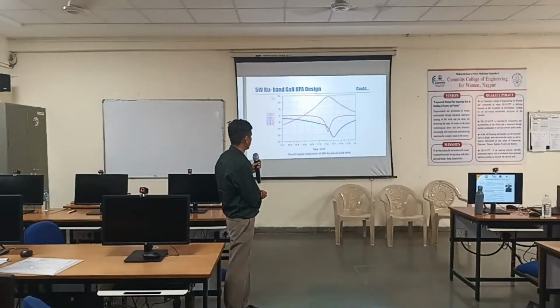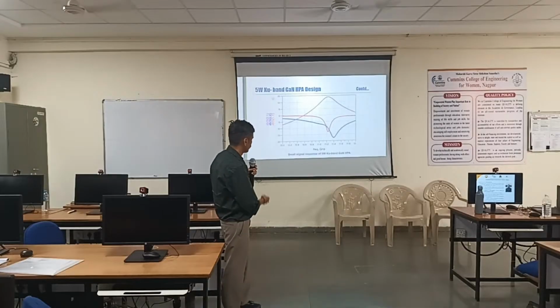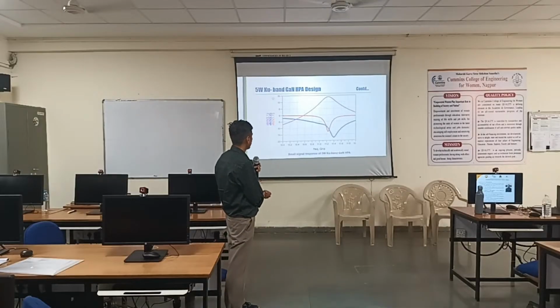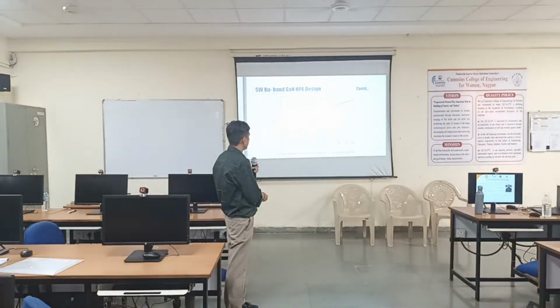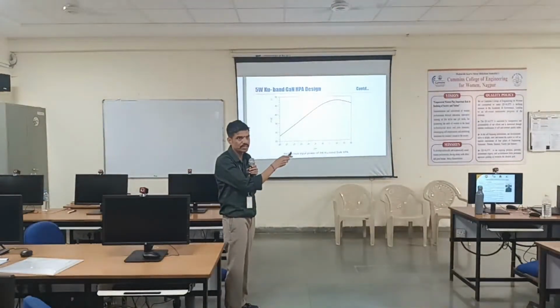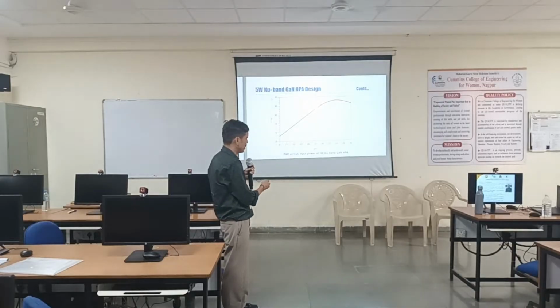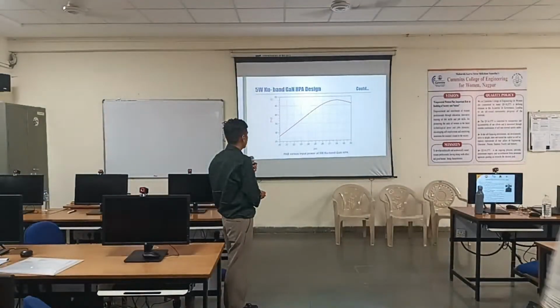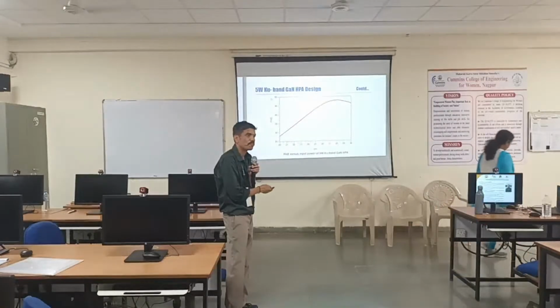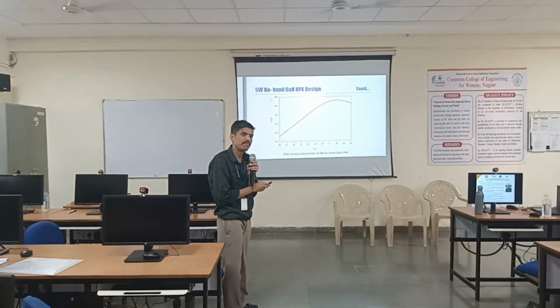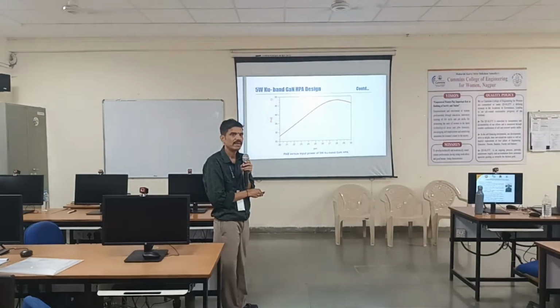LC combination is there. This is the small signal response of the PA throughout 10 to 12 gigahertz. This is the input power versus output power. I'll show you all these results once I start my tool also. But just to maintain continuity, let me show all these pictures. Input power in watts with respect to power added efficiency. So power added efficiency is not only a function of frequency, but also